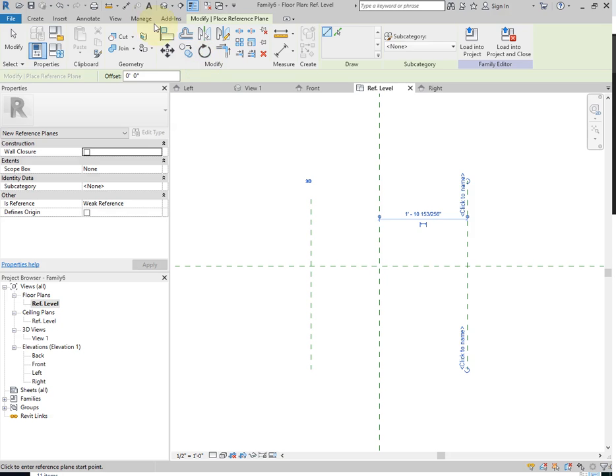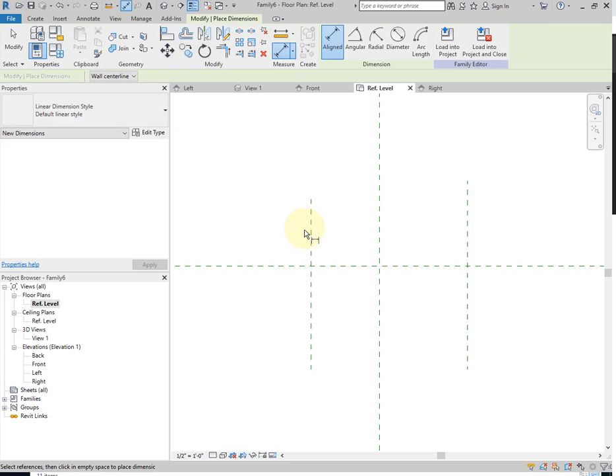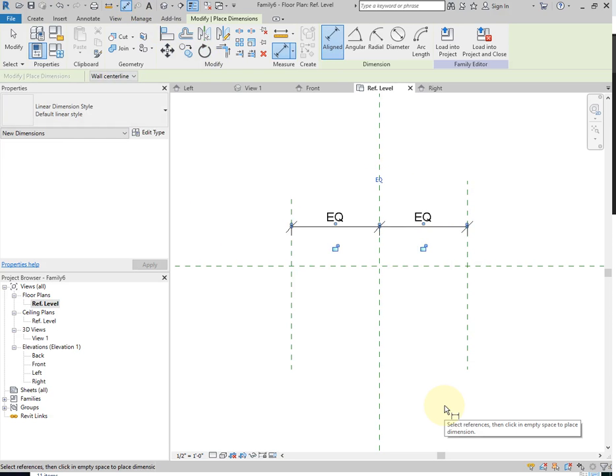And then I use my dimension tools, and let's say I want to make these 2 planes I made on the left and right equal distance around the center. If I wanted to make an object centered about the left-right plane. And now we want to add on a dimension for the overall width of this thing.